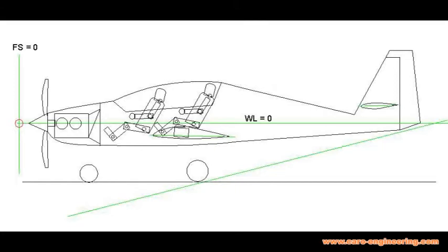Where the wing can be positioned is influenced by several factors. First of all, there has to be room to route the spars or the spar through the fuselage without interfering with other components. The aerodynamic center of the airplane, which is largely determined by the wing, and the center of gravity of the airplane, which is determined by the mass distribution, have to be at a certain distance from each other. The CG must be in front of the aerodynamic center, otherwise the airplane will not fly stable.